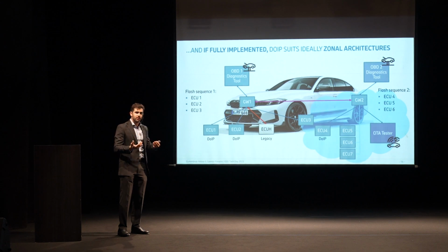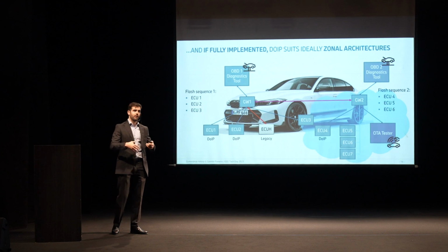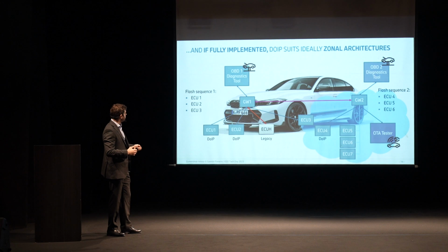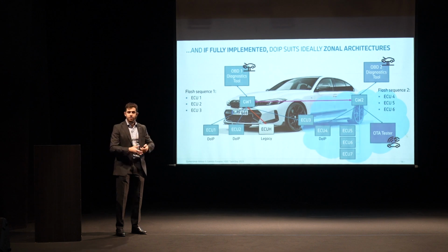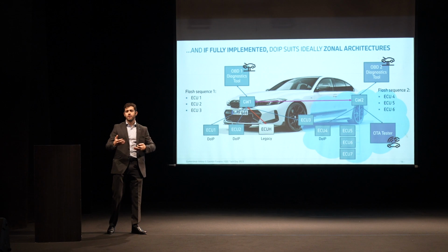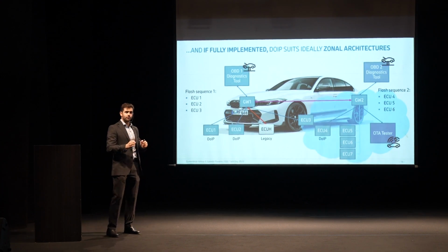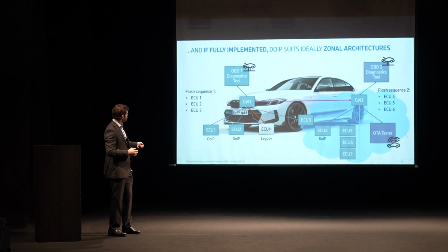This brings us the possibility, for example, to have not just one OBD connector, but to have 2. And then we could, for example, flash faster. We could, for example, take one OBD tool and flash one zone and take the other point of the vehicle and flash another zone of the vehicle. Also, because the number of Ethernet ECUs are going to be increased in the future, the multiplexing of TCP testers is also going to optimize those zone controllers that we see here.